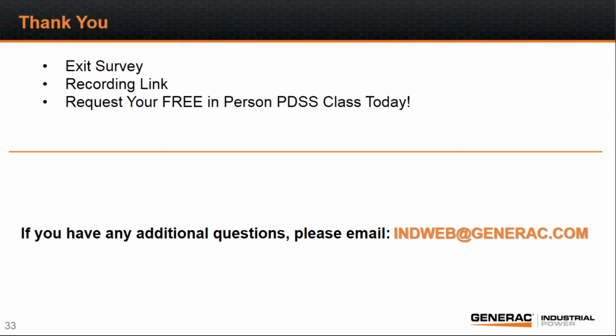So that's something you should always be thinking about. Anytime you're using soft starts and you want to try to match it to a generator, if it's going on the bigger motors, I'm not worried about the small motors, but if it's going on the big motors, always make sure it's a good industrial soft start that can do a nice voltage ramp for you.